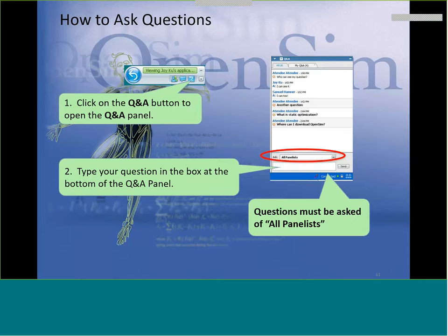We chose it because it's really fast, and I think for a standing long jump, you'll get most of it without letting your model explicitly slip. You'll get a lot of the counter movement phase and extension phase. That being said, I did try some compliant contact, using Hunt-Crossley forces, and that slowed down the forward simulation quite a bit, the integration phase, and didn't really add too much to answering the questions.